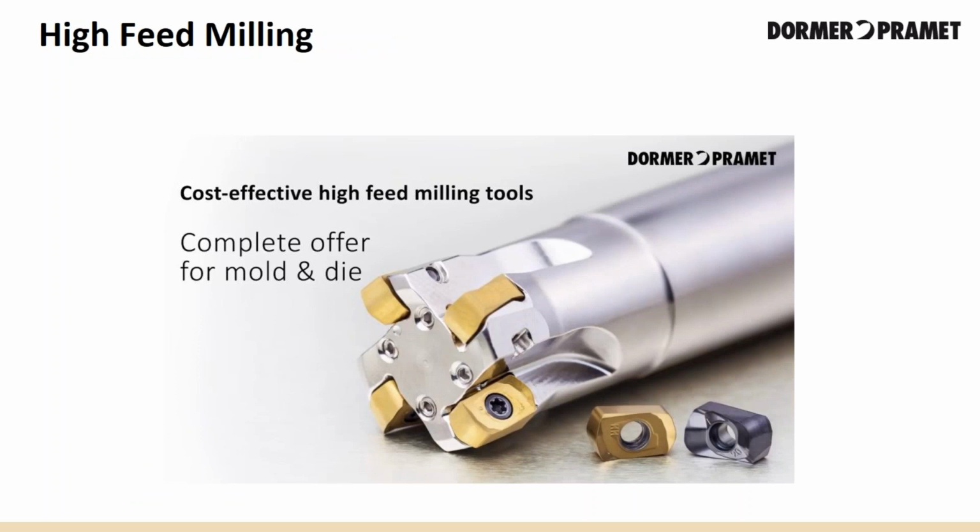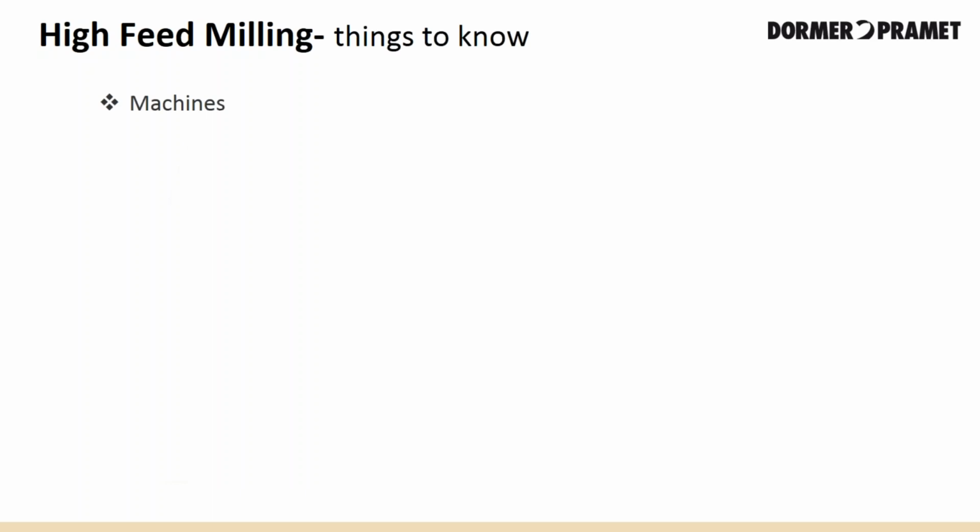So part of that is, high feed milling is about chip thinning. You must increase your feed rate in order to compensate for the chip thinning effect that is created by the large entry angles of the tool. In maintaining the feed equal to the chip thickness, we are making sure that the chip is thick enough to absorb the heat created by the milling process.